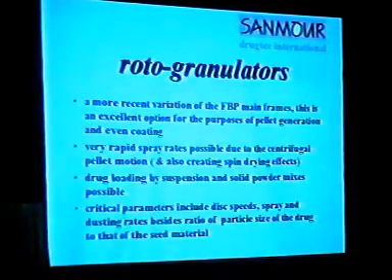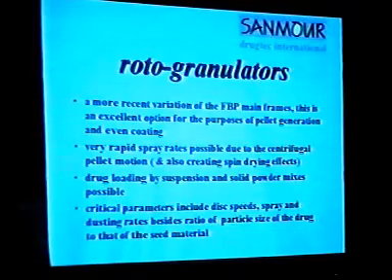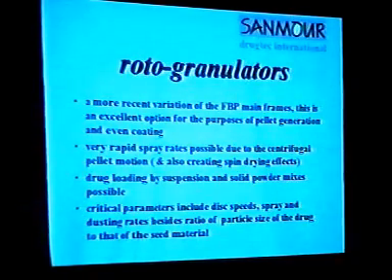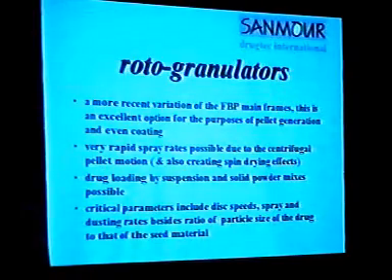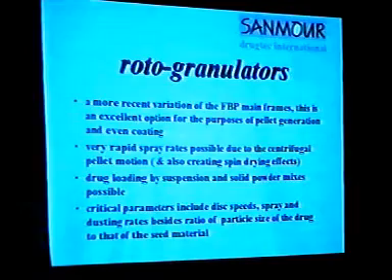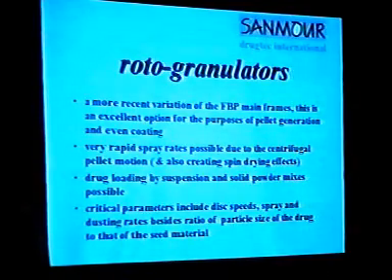Next slide, please. About this evaluation of the fluid bed process mainframe, this is an excellent option for purposes of pellet generation and even coating. Very rapid spray rates are possible due to the centrifugal pellet motion, also creating spin drying effects. Drug loading by suspension and solid powder mix is possible. Critical parameters in this case include disc speeds, spray and dusting rates, besides the ratio of particle size of the drug to that of the seed material.